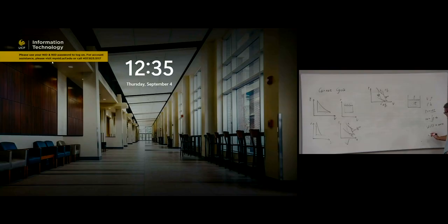And from the first law of thermodynamics, we know that delta U equals delta Q minus delta work. Correct? We give some energy out, we need to take some heat in. Correct? If the output is the work, you need to take some heat in. We can reverse the process. Right now, it's not isothermal expansion, it's isothermal compression. We just push externally. We give some force to the cylinder, to the piston, to push it down. But we still keep the temperature the same.